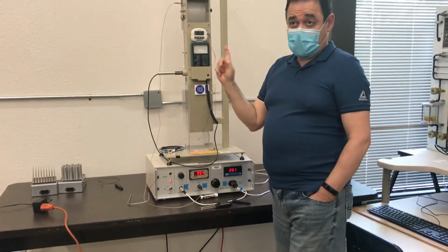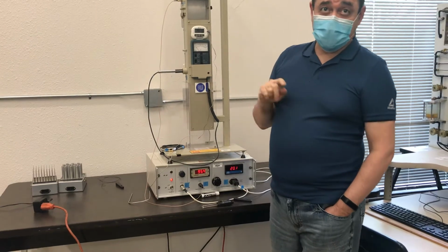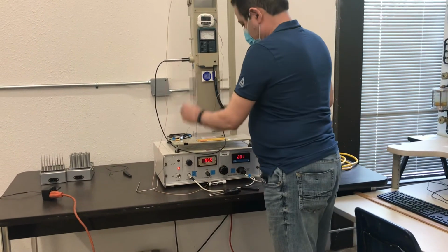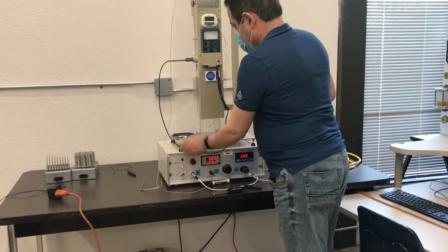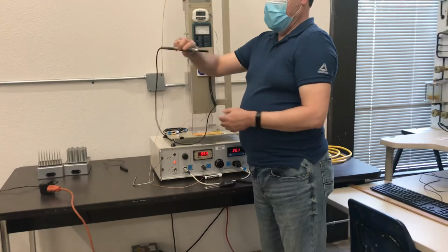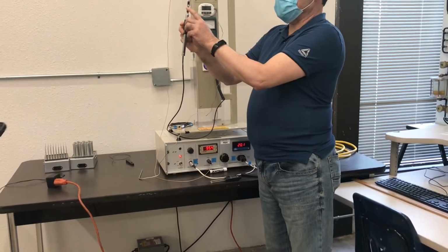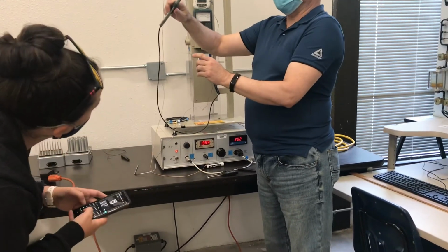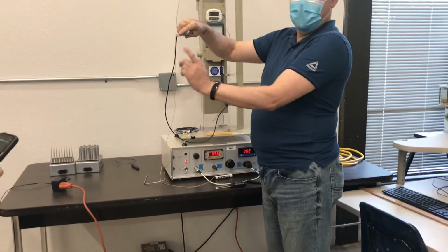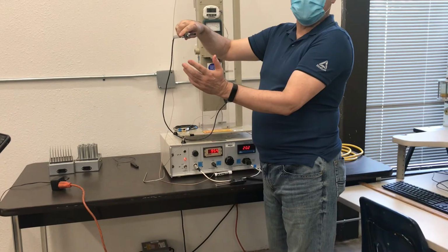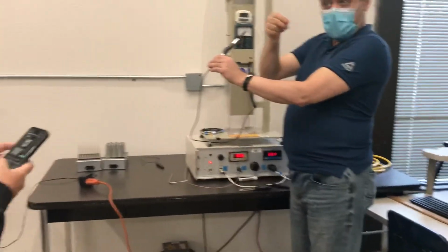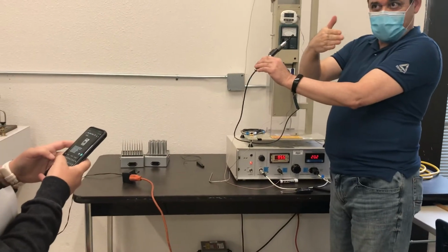Now, a big mistake that a lot of people, even experienced people in fluid mechanics, make is the orientation of this probe. See here? The hot wire is right there. Since the fluid is coming in like this, this orientation is better. But how do you know that it is in that orientation? Just like the pitot tube, remember? You turn it back and forth until you reach the peak value.